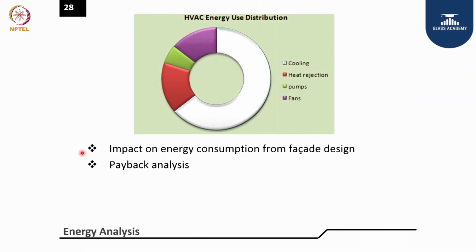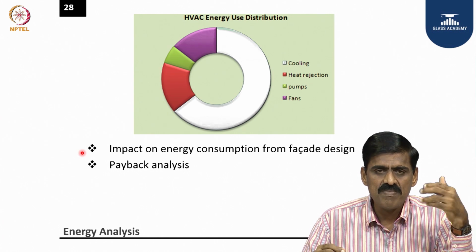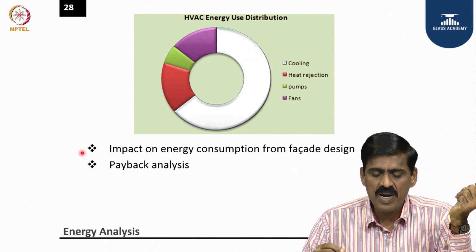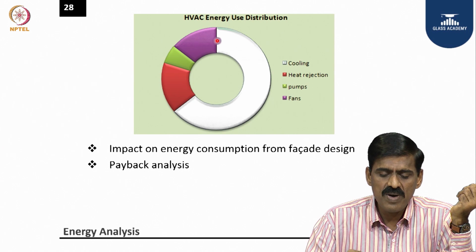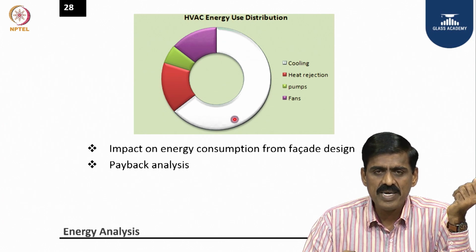And you know very well the HVAC design is directly impacted by the facade. So once you know the heat ingress and you have optimized the facade, the window to wall ratio and the different elements on the facade, then you can look at how to optimize the cooling. Keep working on the cooling and see how we can bring the cooling down for our tropical country.